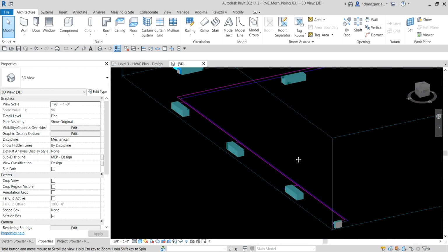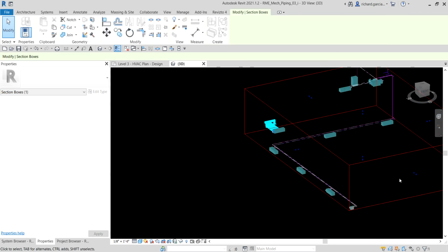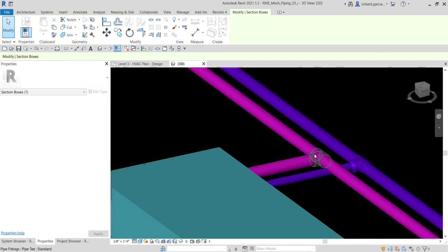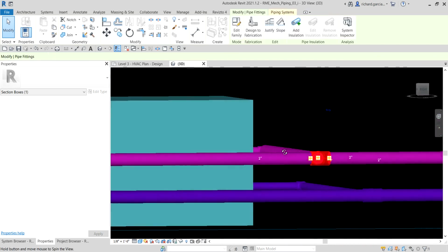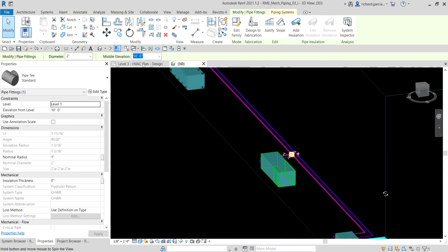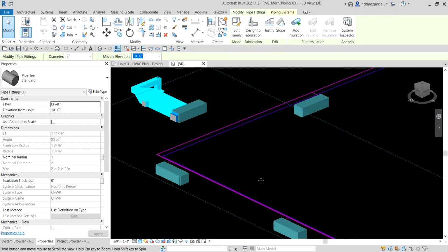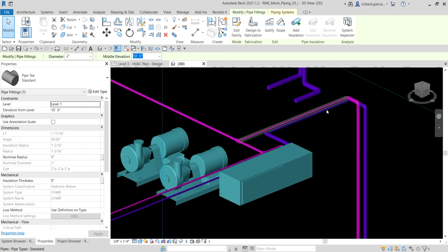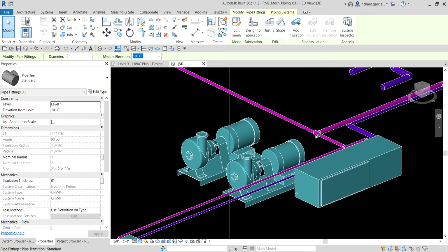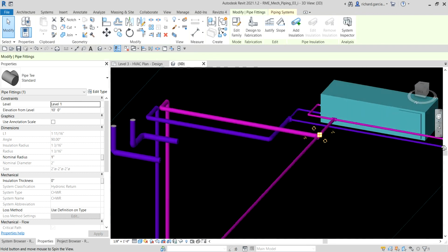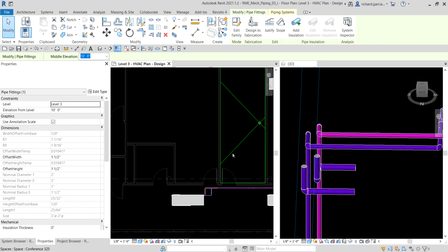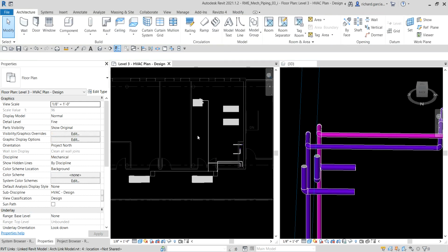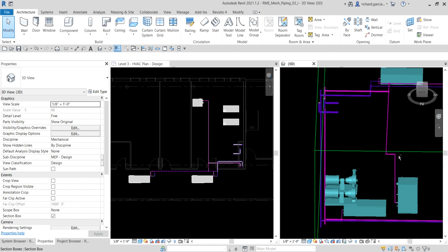So these are the 6 water source heat pumps that we have below, on level 1, and then there are the chilled water return and supply pipes that go up, and there you go. Perfect, right? So there's no clash. Basically, that's how you add a pipe using auto layout, and also how you edit it.